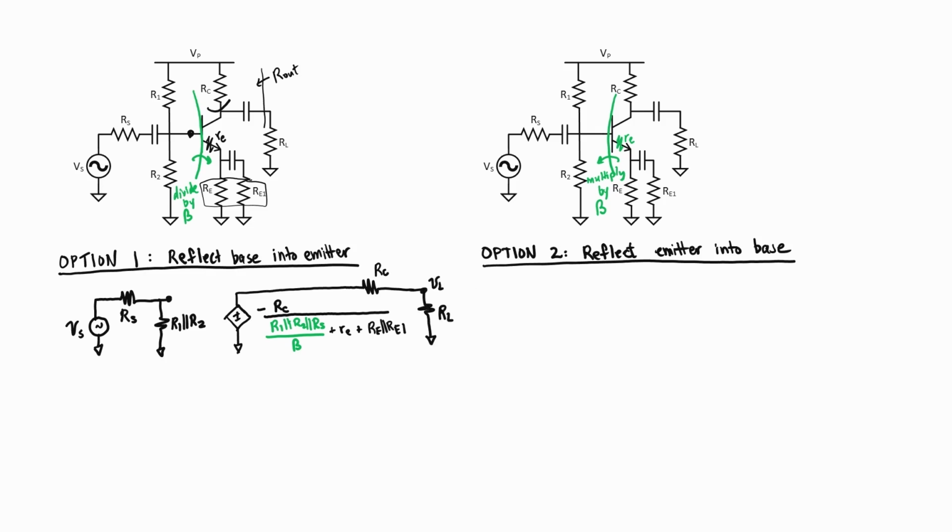This is a simple enough circuit that we can find an expression for the gain by inspection. First we have a voltage divider set up by these resistors. I could call this the input side. Then we have the gain section that's given by whatever we have written next to this source. It's important now to point out that I shouldn't label this V sub B because it's not a true expression for the base voltage. If I wanted a true expression here, then I should use impedance reflection on the right side. I'll label it V sub 1 in order to take care of that technicality.